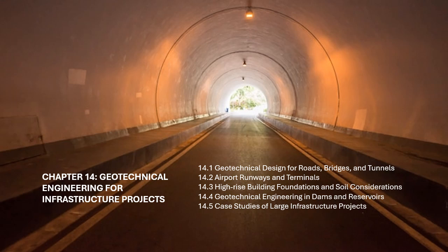Geotechnical considerations. The foundation of a gravity dam must be carefully evaluated to ensure that it is capable of supporting the structure without excessive settlement. A concrete gravity dam requires the soil or rock beneath it to have high shear strength to resist sliding forces. Engineers must also evaluate the potential for cracking due to thermal expansion and contraction of the concrete.